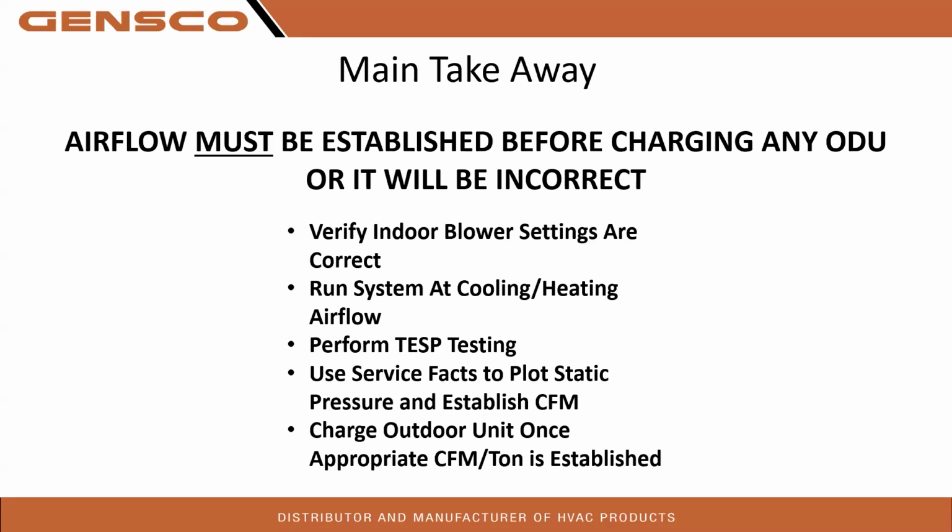Perform total external static pressure testing. Verify what the resistance is in the ductwork. You can plot that CFM and plot that static pressure on the service facts to see what our CFM is. That's what the manufacturer wants to see. That is what Trane is going to want from us when we tell them about airflow and its problem system. They're going to want to know what the speed tap is, what the CFM settings were, what our static pressure was, and where that number lands on that chart.